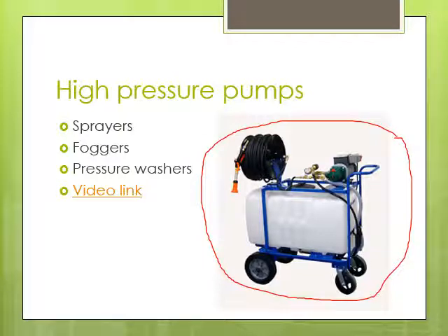These things, it's really important to maintain the pumps. Something that I ran into with my farm is I didn't use it enough, and it would start to corrode because water was sitting inside that pump. Keep an eye on it. Run it periodically, even if you're not using it that often. There are instructions for some systems to put oil in them so that they don't corrode if you're not going to use it for a long time.